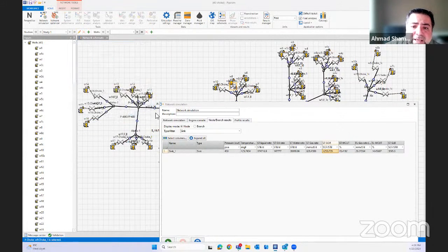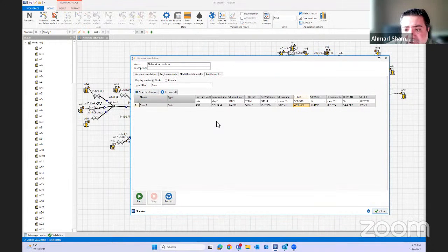Since I know that the GOR of the wells are different, I would like to reduce the GOR. Let's say, for example, I would like the stock tank gas rate not to be more than maybe 580, but at the same time, I'd like less contribution of gas to come from the wells with high GOR. So I'd like to have more oil come. How do I do that?